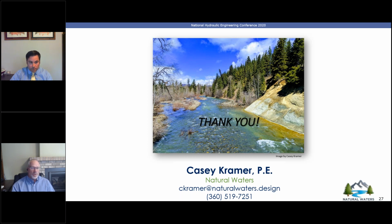I certainly recommend, where we can, if you've got a box culvert on the main channel, so it's a main line structure, modeling that box culvert as a pressure flow bridge rather than an HY8 1D structure. As time goes, we are certainly looking into integrating circular conduits within the 2D domain, but that's probably a little farther out. So the best practice we have now is to insert that 1D solution for 1D structures within the 2D solution.